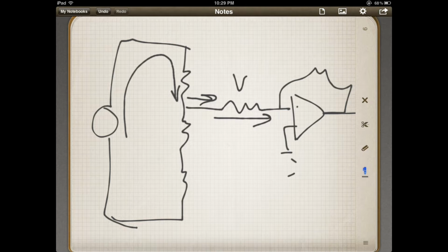You basically create another voltage divider, because inside here, it basically goes through here and goes to ground. That's what it's going to do, since you grounded that input. That will actually cause the voltage at this node right here to go down, because it's robbing current from it. You're going to have a voltage drop, right? So you may not want that.